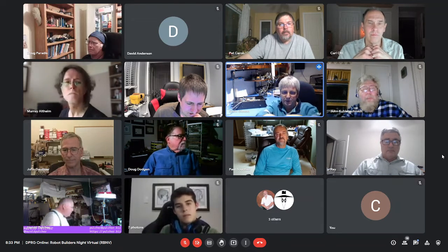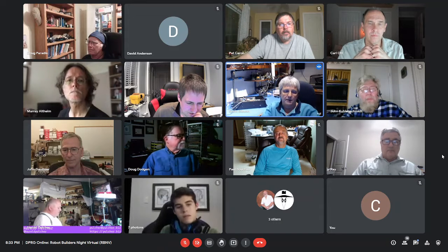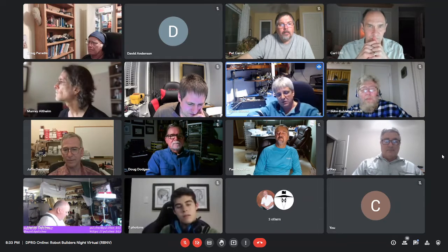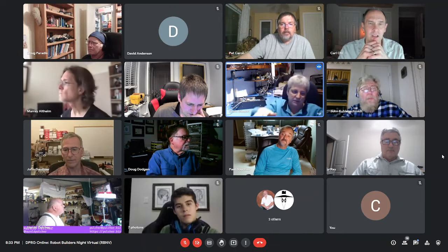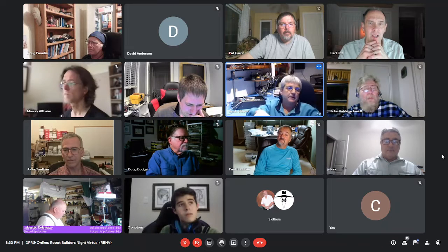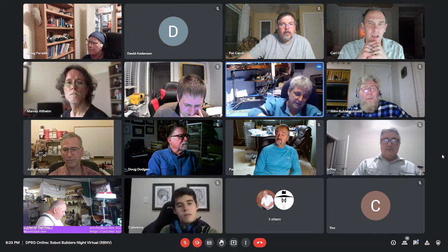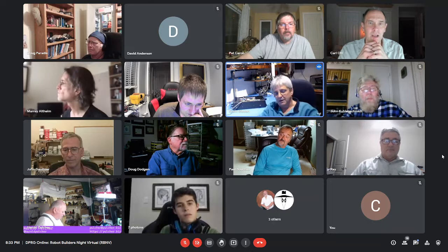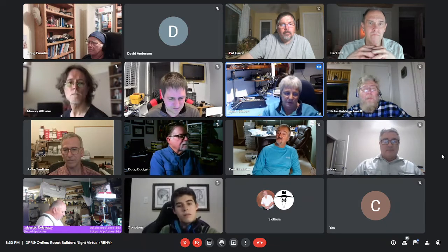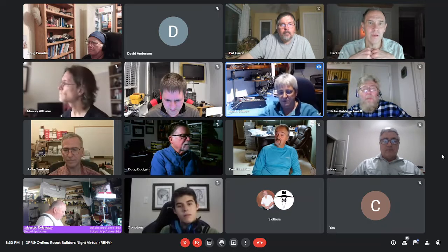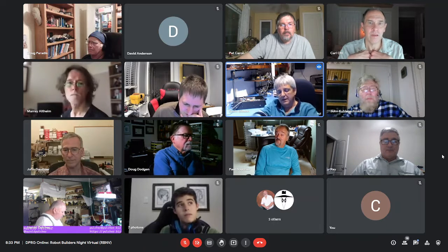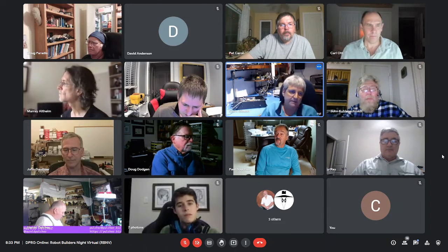It doesn't puddle up and create a crown, where, since there are no legs to create surface tension to pull it down to the board, it just seems to muddle on top of that crown, and you always get uneven connectivity on one side or the other, depending on where the crown takes it. But when you window it and have several small squares, then it lays flat and it'll pull right down.